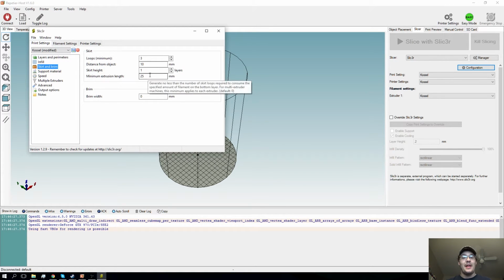I have the extrusion length, actually, this is 25 millimeters of filament, not of actual movement on the bed, so it actually will extrude like 6 or 7 loops, which is why I use this for smaller parts. If you have a smaller part, it's only going to make smaller circles around it, so you want it to be a little longer to make sure everything's primed up. So that's why that's that. Again, these are kind of arbitrary numbers. You can put whatever works for you, but this is just what I know works.